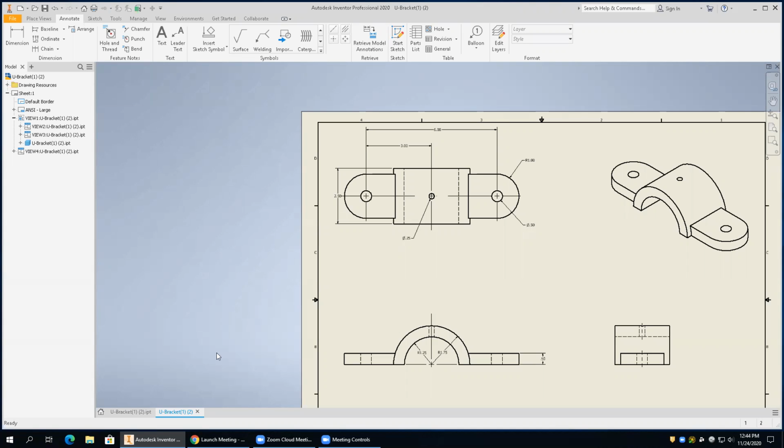Okay. So if we wanted to change this, that's a yes. Say what's in the model. Go to the model. Here, you have T5. There you go. Now go to extrusion 1. Open up extrusion 1. Go to the sketch. All right. See the number 5 at the bottom. Okay, make that 6. Okay, go ahead and finish your sketch. Notice it fixes your model. Go back into your drawing. See how it fixed it?